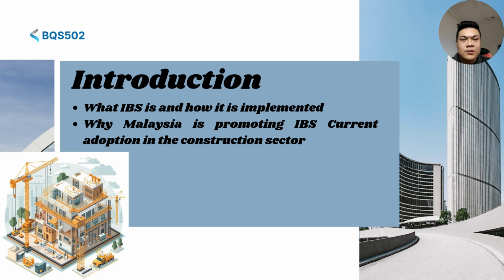Next is the transportation to site, where the IBS components are delivered on a schedule using transportation vehicles to avoid storage issues and damages. Next is the on-site assembly, where using cranes, trained installers assemble the components like a building puzzle, where the IBS is already constructed at the factory and just placed on site. This is to ensure the construction becomes faster, cleaner, and safer because there is minimal work to be done on site.